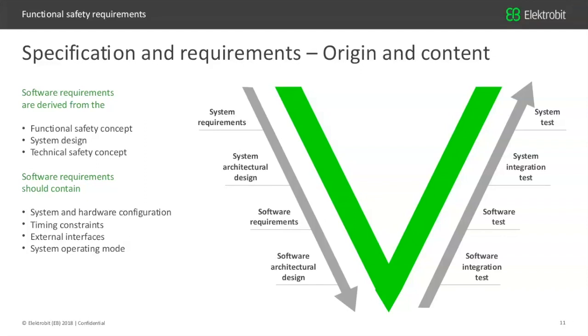my safety requirements, and they should actually address things like my system and hardware configuration, my timing constraints, so worst case execution times, things like that, my external interfaces, of course, where there needs to be communication, how I interact with my environment, and the system operating mode, which means that I also have to consider my safe state or other system operation modes.